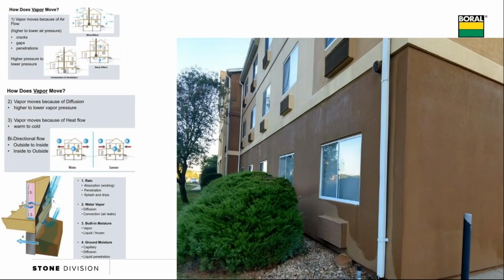The last piece that I want to set as our foundation is around moisture. Vapor and liquid water are constantly moving in and out of our buildings. I would suggest that really every cladding leaks. It's how prepared we are behind the cladding to deal with that moisture. You don't need to read all these little things here. They came from a company called Dorken.